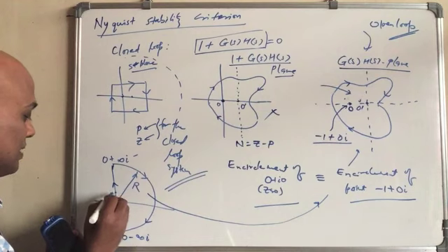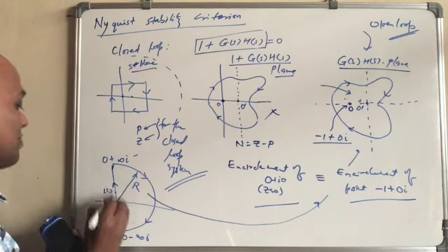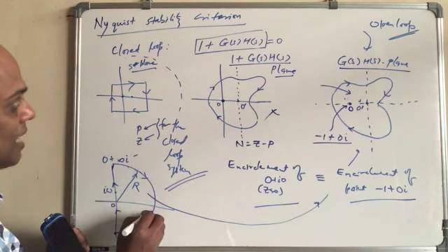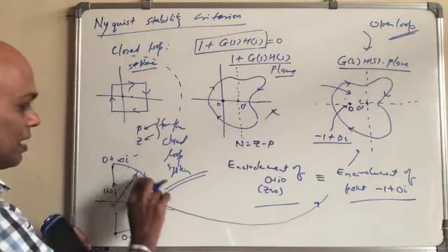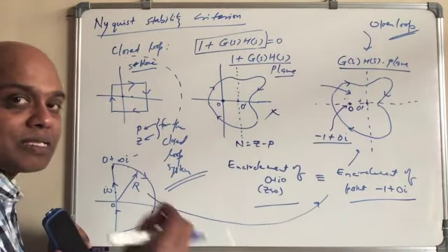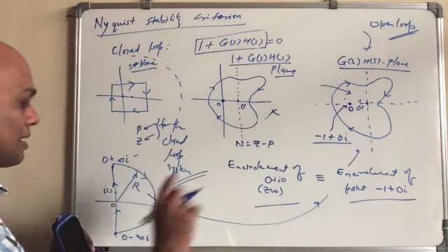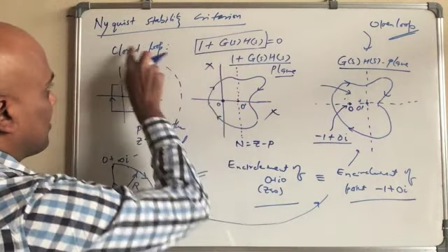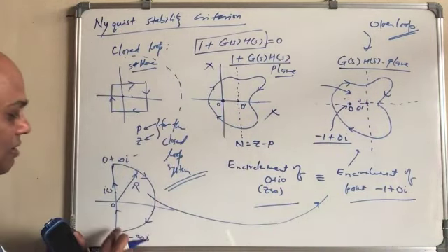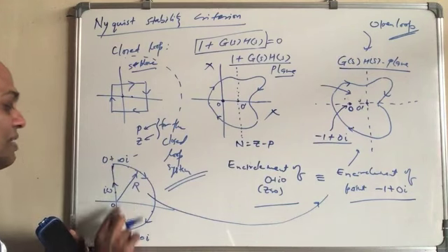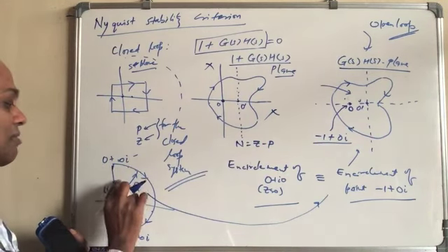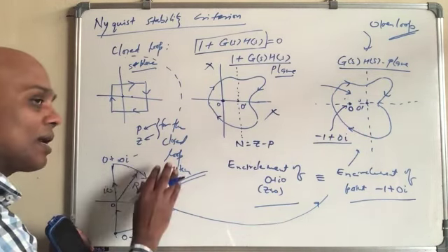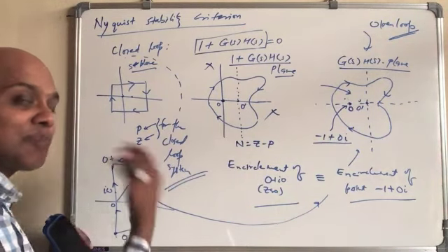In between, this will be some value, I omega basically is changing. And here we are assuming that the value of this is finite. It will not be infinite, some finite value, but the same value. We will look at that later. Now, what we are doing, we are skipping this one. We have the S plane, and we have this contour which is an infinite semicircle, so that we cover all of the right S plane, so that we capture all the unknown zeros and poles.